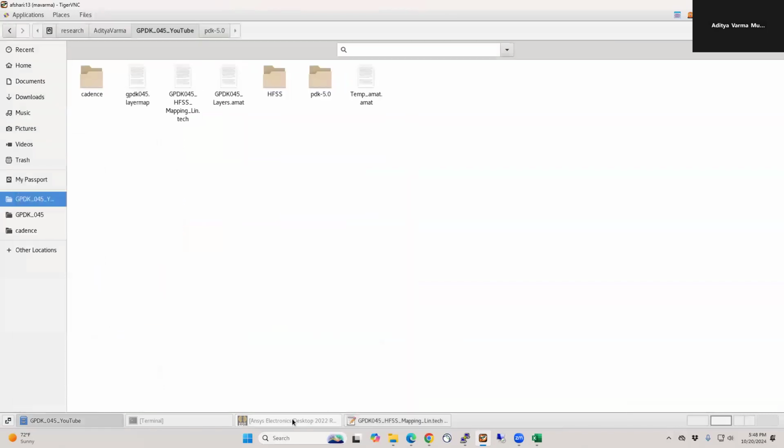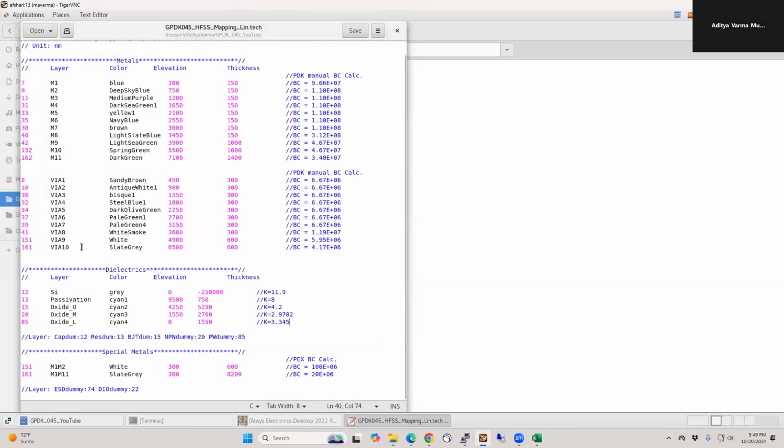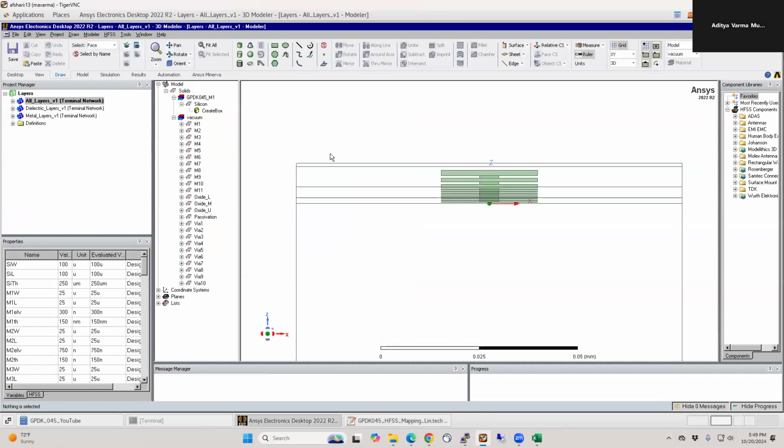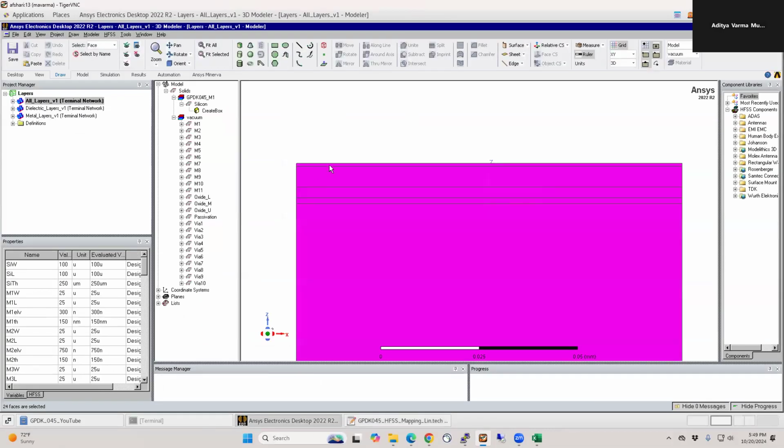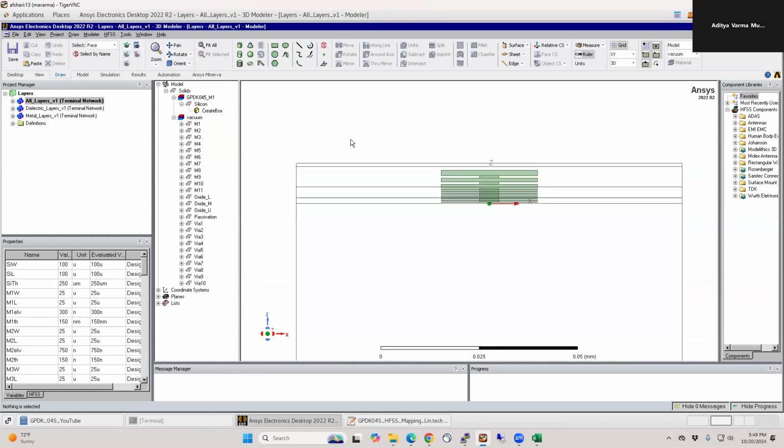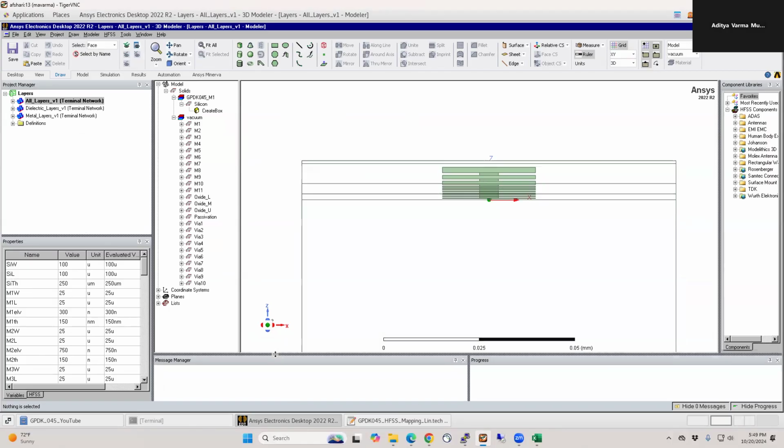What you can instead do is just import all the metal layers and these via layers, and we will import all of these. We can just copy paste all the dielectric layers from this HFSS file because I made all of it parametric. So for example, you can change the width and length of all the dielectric layers in these parameters. So that's my personal preference. But we'll do an example and see how to do all of these, going back and forth between different layers.